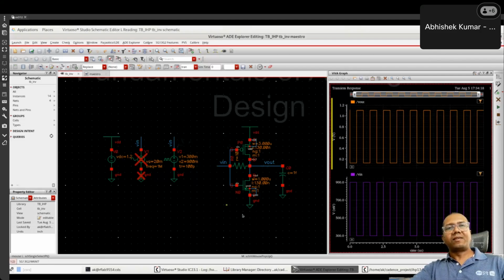So the same kind of digital circuit, which is designed for digital processing, can be tweaked to be used for voltage amplification. The whole point is we have access to this CMOS technology, which is designed to advance digital processing. But at the same time, we also have the requirement of analog processing. You have to take the signal from the microphone, do the conditioning, then digitize for further processing. Again, you take the output and amplify it to drive a speaker. So you have this